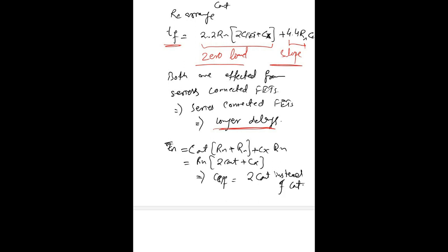It means that our capacitance is increased, which basically means more time to discharge this capacitor. So we can say that the series connected MOSFETs have higher capacitance as compared to the parallel connected MOSFETs. So we will have longer discharging time, and a longer fall time here.